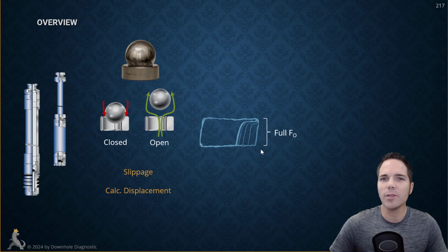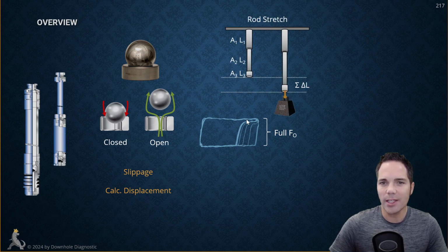We're going to look at the fluid load. What is the fluid load? The fluid load is the weight that is being borne by the plunger, and the rod string is picking that up on the upstroke, as we see in our downhole card. So we're going to talk about what the fluid load is, what affects it, and then how it creates rod stretch, which takes away downhole stroke length as the rods pick up the fluid load.